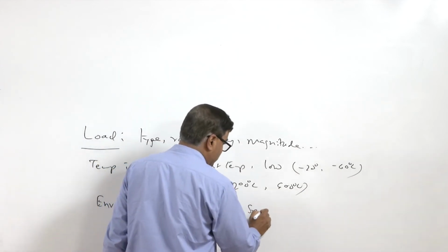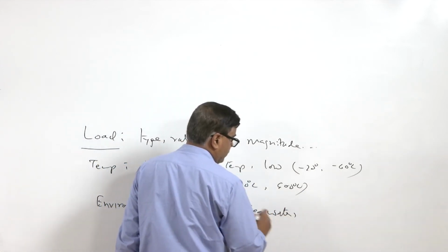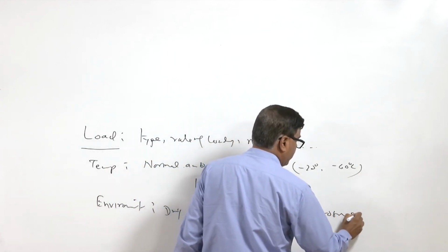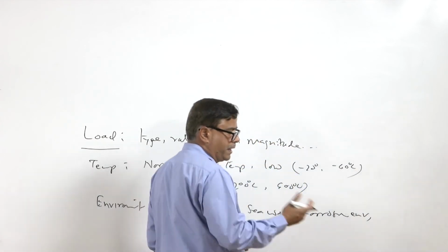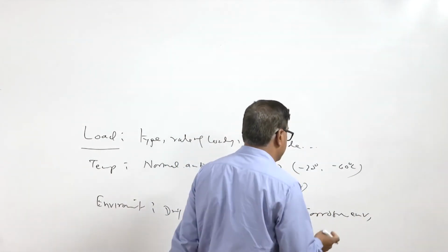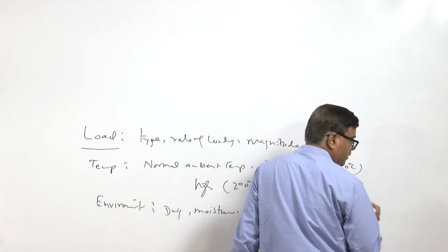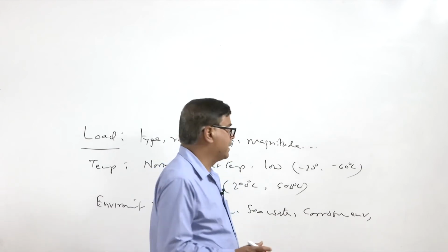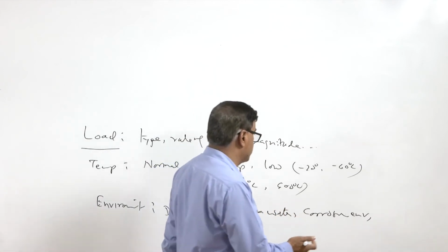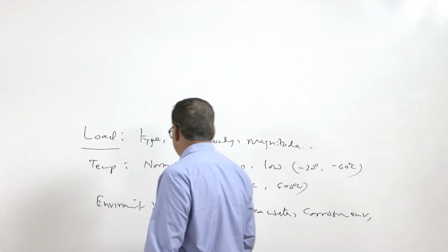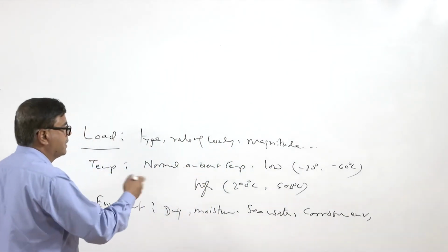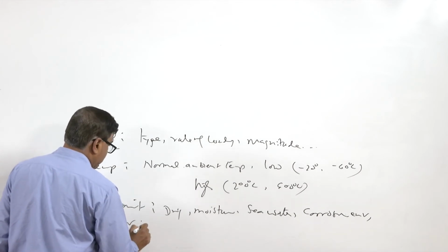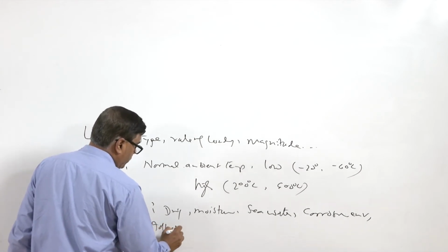or it may be sea water, it is to be designed for sea water, or it may be a corrosive environment like hydrochloric acid or NaCl, like in case of the sea water, or the liquid metal, like a number of components are used in contact with the liquid metal like zinc and magnesium, etc. So, the resistance of the component has to be checked against those environments, and then accordingly it has to be used. And if it is a kind of special condition, then like wear, for which kind of wear it will